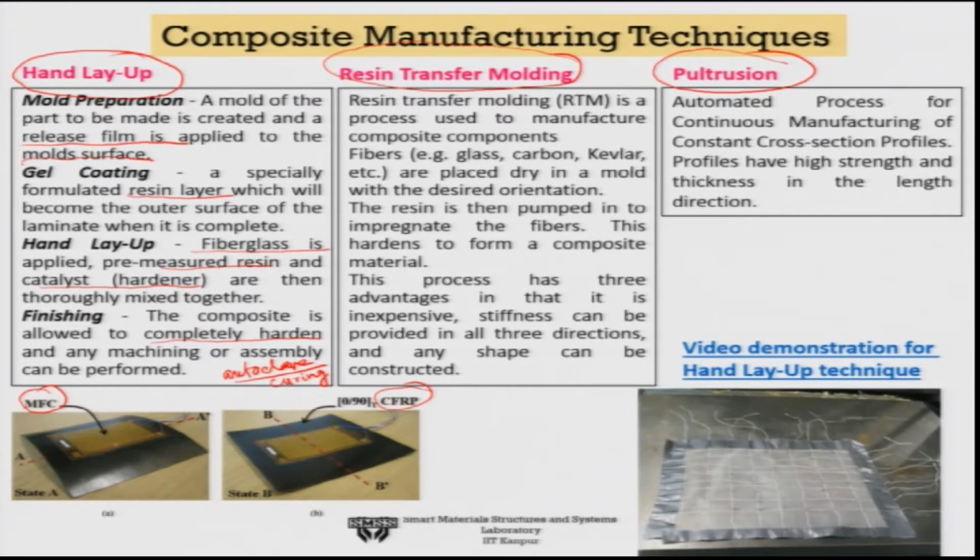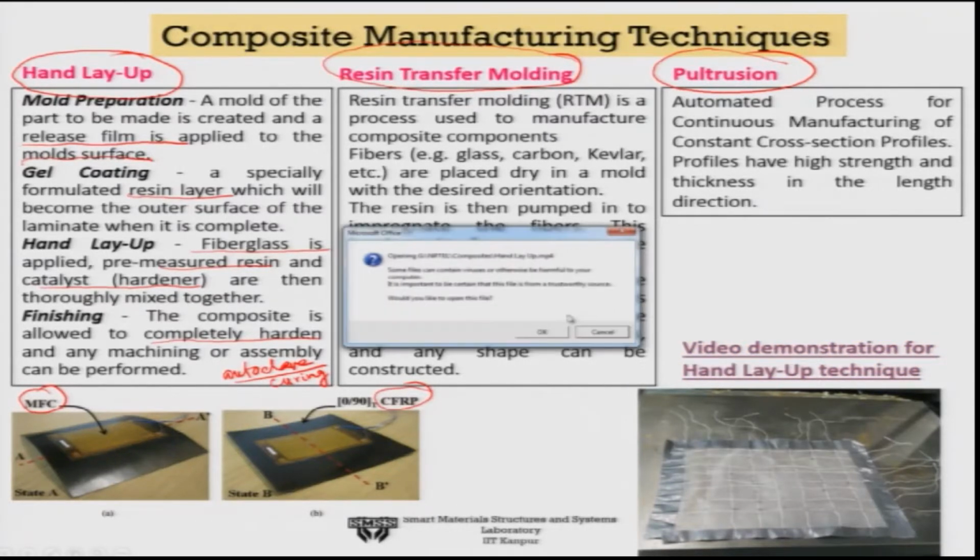We can either surface bond the macrofiber composite, or in another way of doing it, we can embed the macrofiber composite inside the system. Let us look at a very brief video in which I will demonstrate to you the hand layup technique.